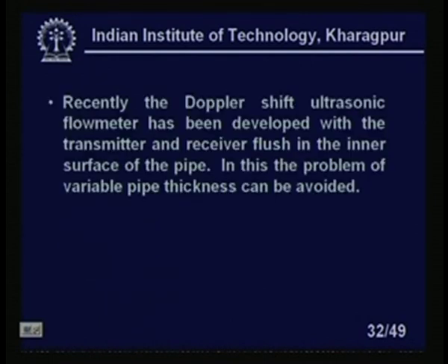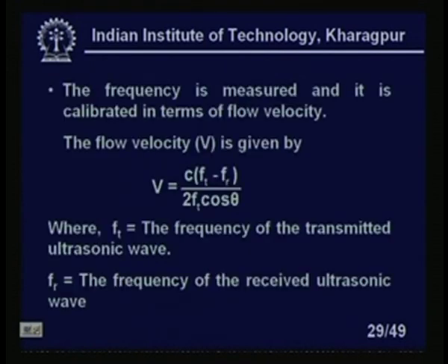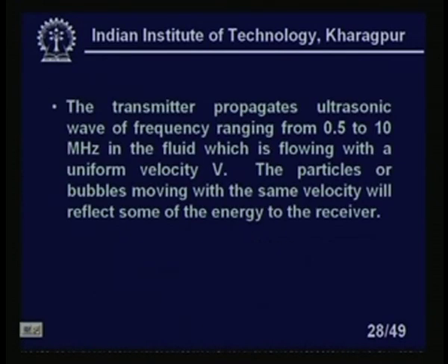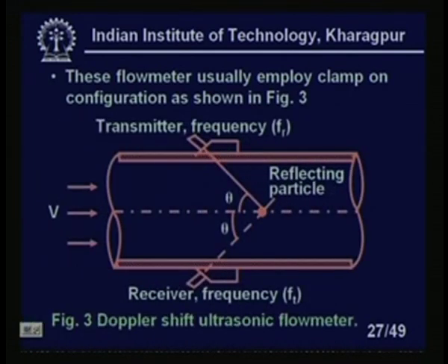If I look at the ultrasonic flow meter, you see here, this is the wedge inside which we have put. So, the velocity in the wedge is more important at that time. We must know that accurately also, right. So, those are the problems with the ultrasonic flow meter. Because there is refraction of the ultrasonic wave also, people now want to flush it with the liquid itself.